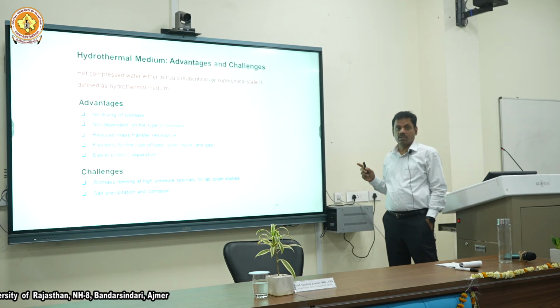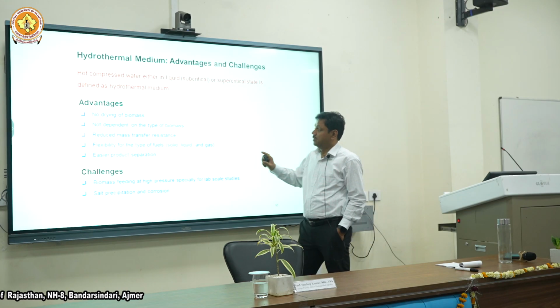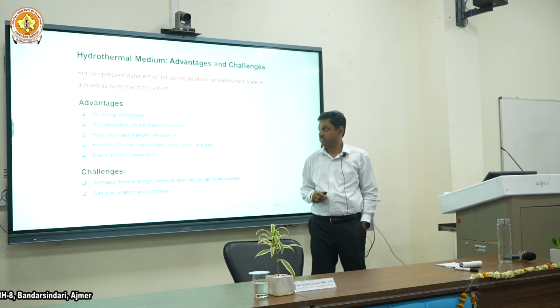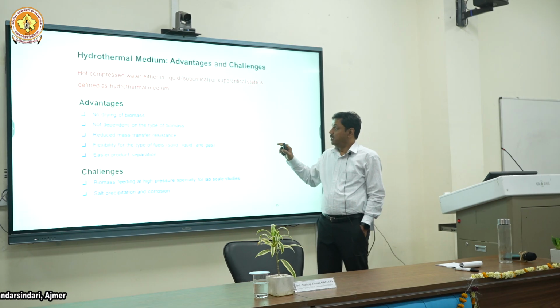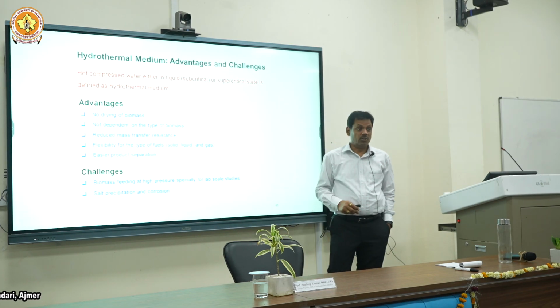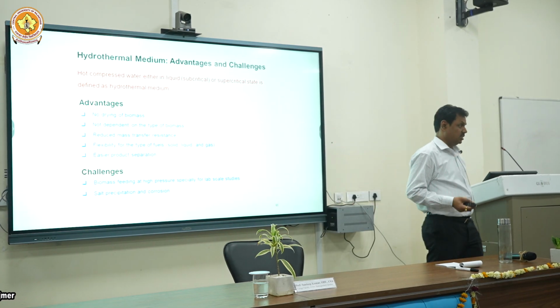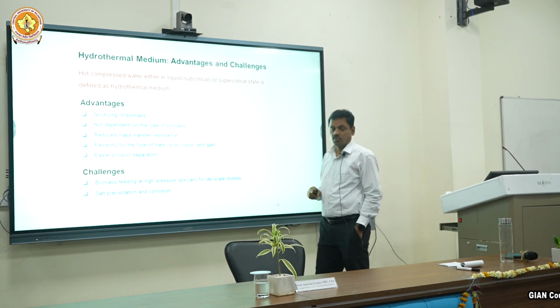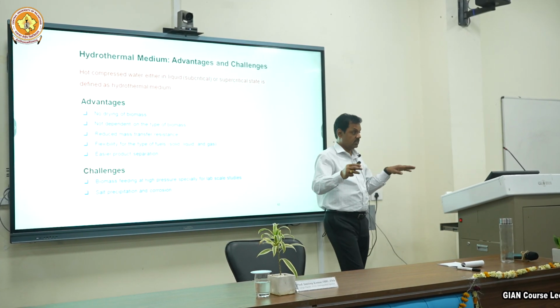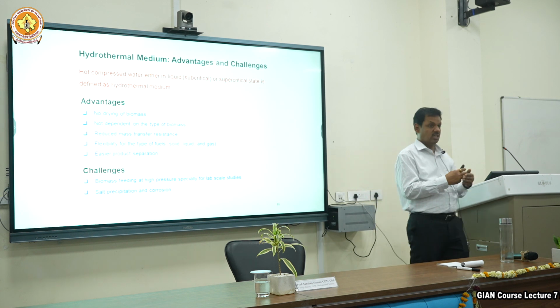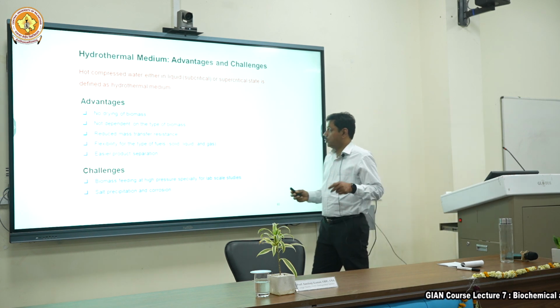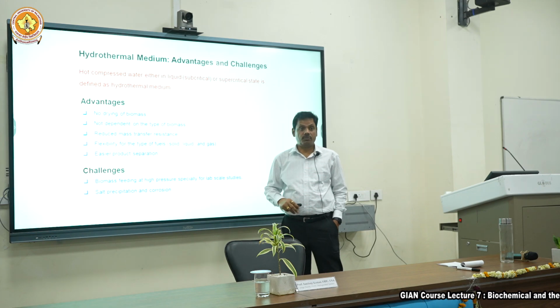So the advantage of using water is that you don't have to dry the biomass. It's not dependent on the type of biomass; grass, wood, everything can be used. Mass transfer is also reduced, because water can penetrate very deeply, giving deep mass transfer regulation in space. I'll show you how you can make a solid fuel, green coal.